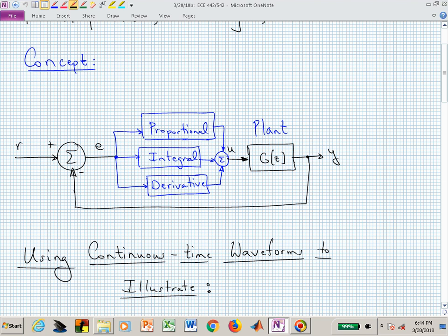That taken into account, or another way to think about that would be the integrator is worrying about steady state accuracy. If you want to try to improve your steady state accuracy, you might want to involve an integrator or introduce an integrator. If you're trying to speed up your system behavior, you may want some derivative action, the D. Question?